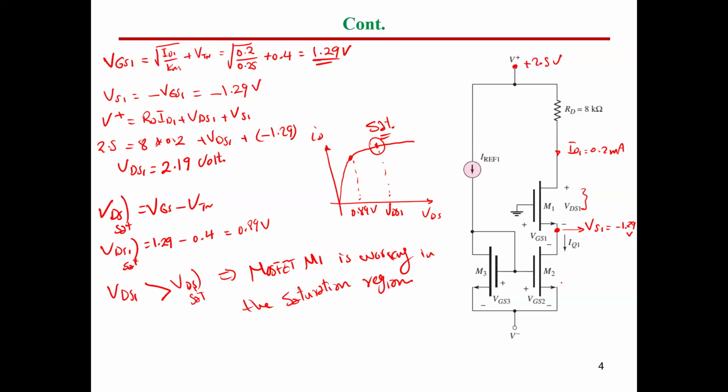So we forced this branch here to have the same current. By the way, if you have another gate here that's not connected to ground, I don't care, but by the end, since M1 and M2 are connected in series, by force, the drain current will be the same.